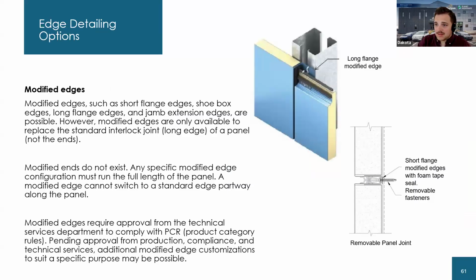Of course, with modified edges, we are talking about a particular panel today that has systems where it's going to be exposed, kind of a premium looking finish. Just know that the steel, if you're wondering about how that joinery connection happens in a horizontal application where the IMPs are not clicking together through that joint, is like what's being shown here. Another IMP is ready to be stacked up here, but what happens at this nice flat surface? Well, we've wrapped that corner with that steel, and then we've added this pressure-fitted rubber gasket so that we have this nice black line.